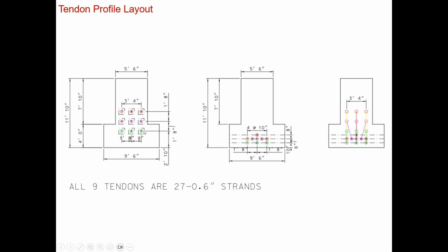So for this one, for example, we had those 3 tendons, 1 through 3 at the bottom, just moved vertically, pushed vertically downwards to make their way to the final position here at mid-span. You can see here tendons 4 and 6 are the only 2 tendons that we picked to move horizontally, both laterally and vertically, until they make their way to the second row. And then finally 7 and 9 are only pushed vertically in the same location, and 8 was pushed vertically to make its way to the third row. And this even gives us an advantage. Even if we need to add additional tendons in the design process, we can always add additional rows here, and we still fill in the row mid-span.